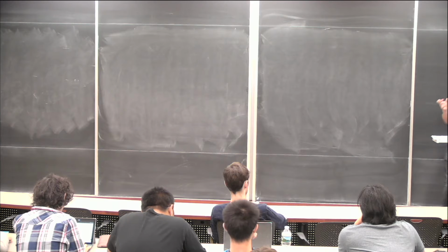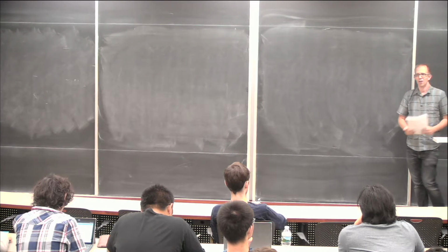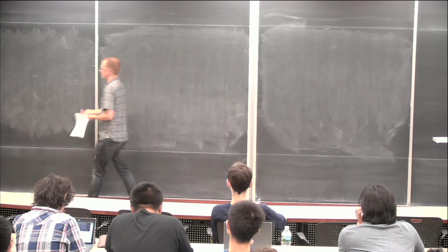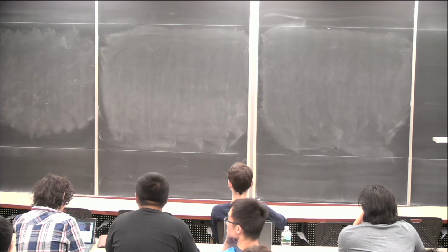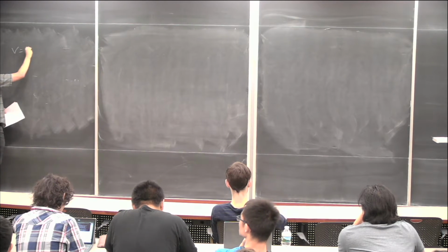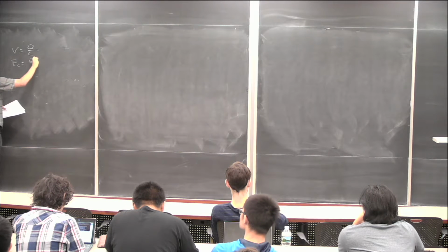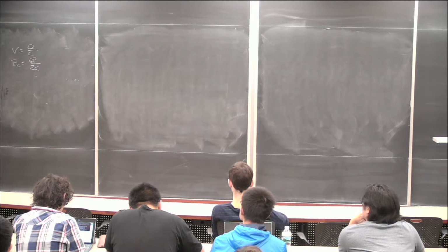And so that is the goal of circuit design from the perspective of quantum computing: to take superconductors, which give you a logical zero, and try and add structure that gives you some well-defined, well-characterized state. From my EE hat, if I'm not thinking about superconductors, we basically only have two tools at our disposal. If we don't want to add resistors, we have capacitors. And if you remember from freshman physics, the voltage is the charge divided by the capacitance, and the energy is Q squared over 2C. We also have inductors.